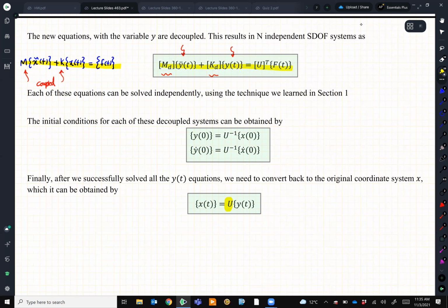Hopefully, some of you studied all those integrals. And later, when I started working in the lab, where I did vibration analysis, I realized that without Fourier transformation and without eigenvalues and eigenvectors, that lab would be closed. You cannot really do anything. So there are applications. You will see one here: the eigenvectors give you the mode shapes, or the U matrix, and the eigenvalues give you the natural frequencies, right?